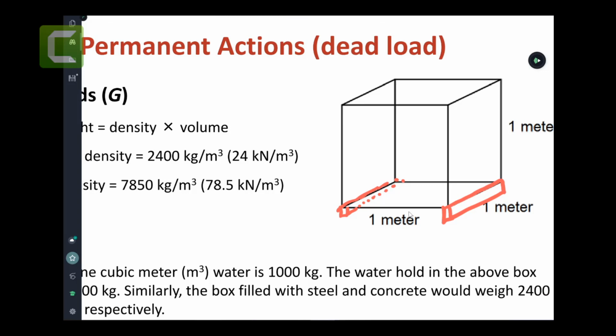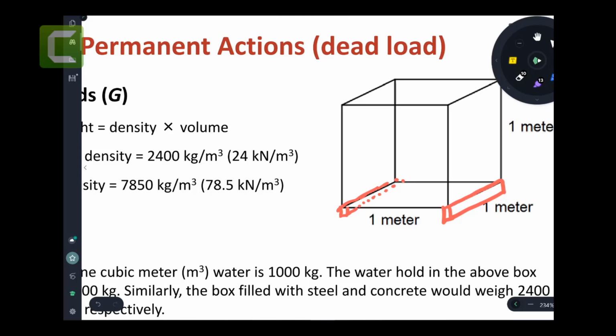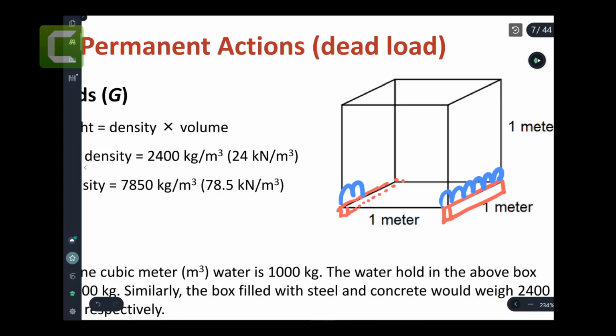A line load. Excellent. That was the answer. In an example like that, we will not give you this answer; you need to imagine it, because the load here is going to be distributed like this. This is a line load. This red beam will end up carrying a line load, whether you like it or not, because that's how the slab is sitting on the beam. It's not sitting by a point load.